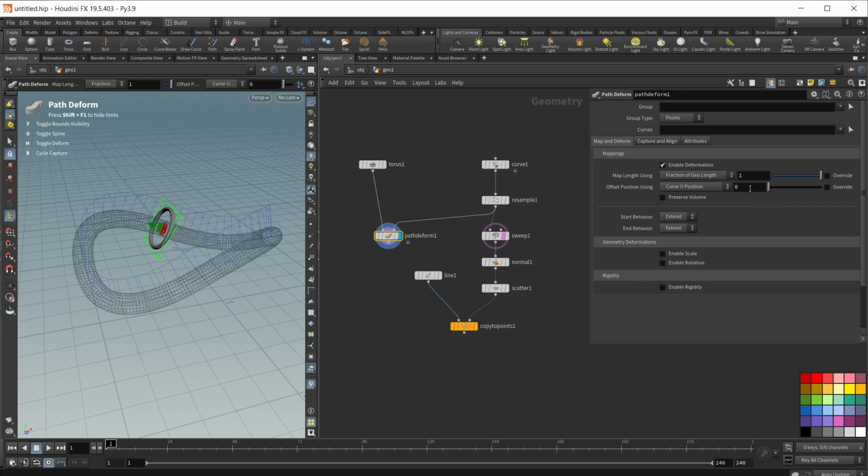And in this case, I want to use not $f, but $t. $t is the current time in seconds on my timeline, which in most cases is a bit more handy than $f, because if I later want to change the frame rate of my animation down here, my animation does not change. So in this case, let's write $t, and I also multiplied this by a value of 0.1.